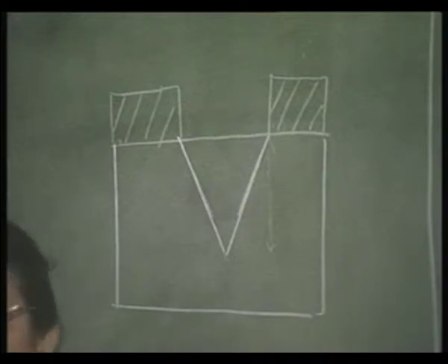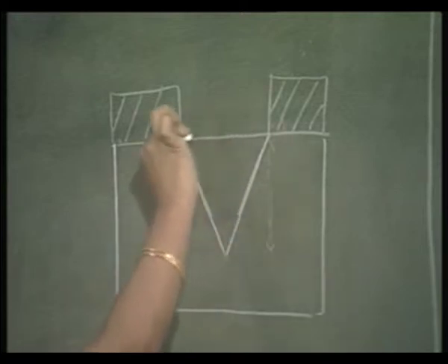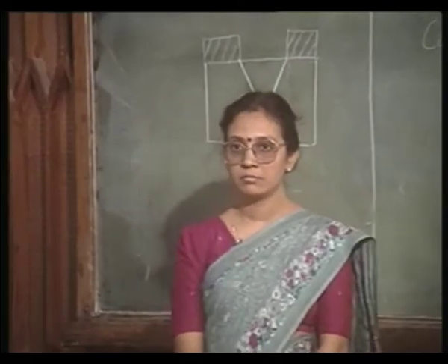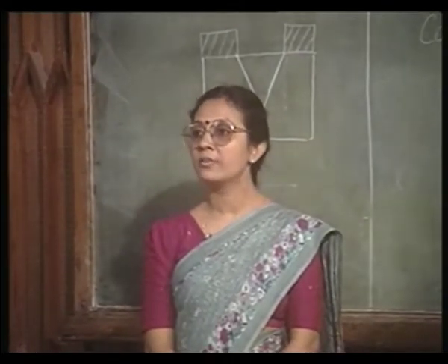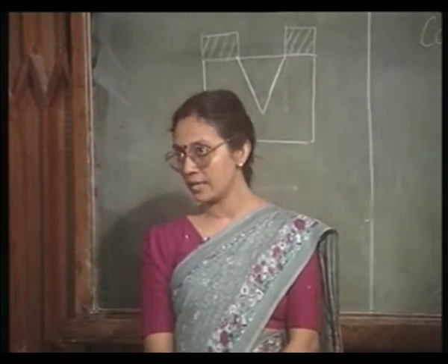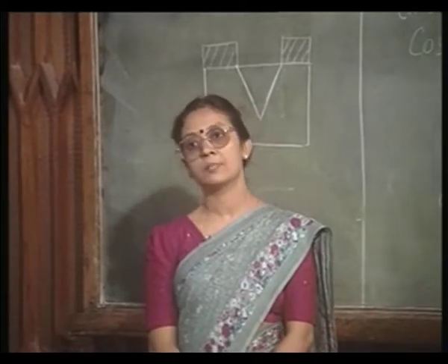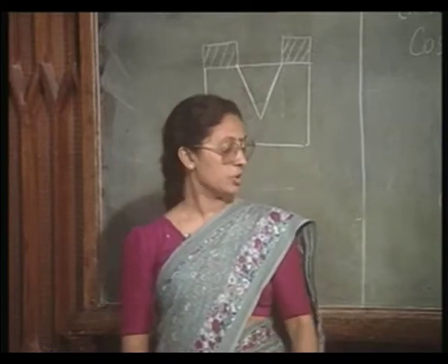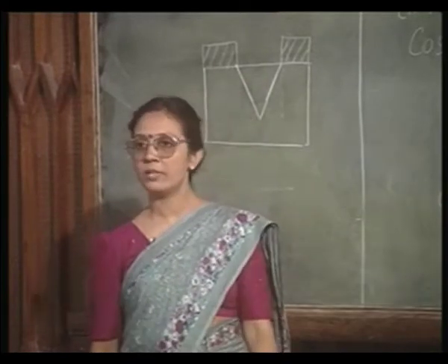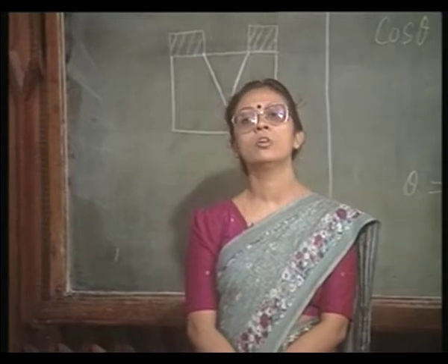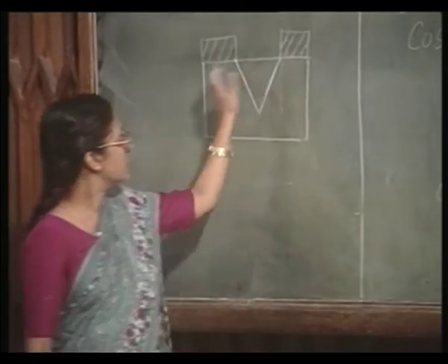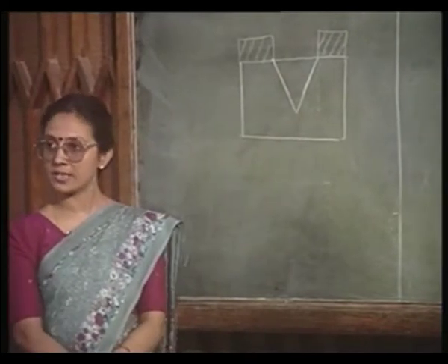Therefore, I am governed by this window opening to know finally how much I can etch. It will be a self limiting etching. Etching will finally stop at a point, no matter how long I keep etching it. So, this is actually a very useful property of the 100 wafer, and it has various applications.